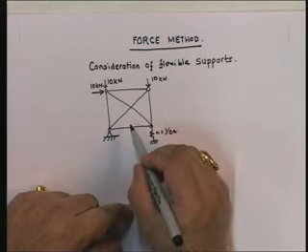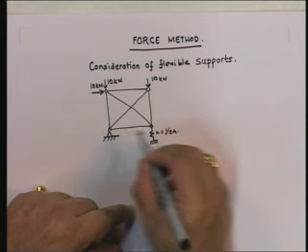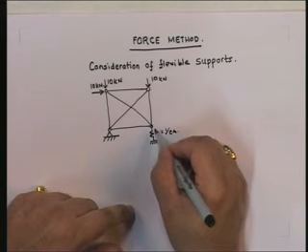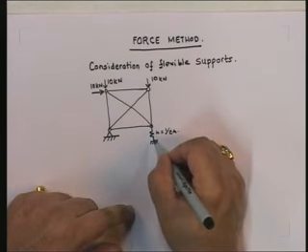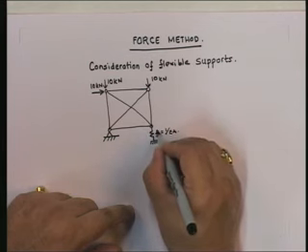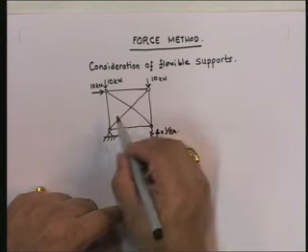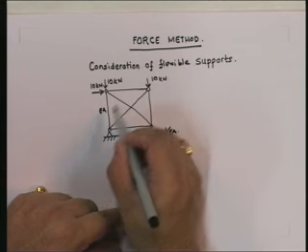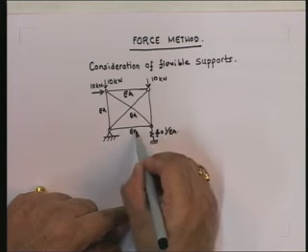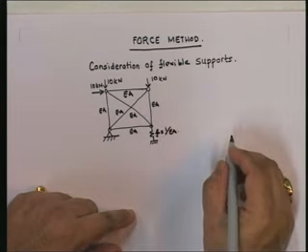So, let us look at what we have. This is the same truss that we had considered last time, excepting that the roller here has been replaced by a flexible spring support, where the flexibility is given as 1 over EA, where EA is the axial rigidity for all the members. All of them are EA. If you remember, that is what we had considered last time.